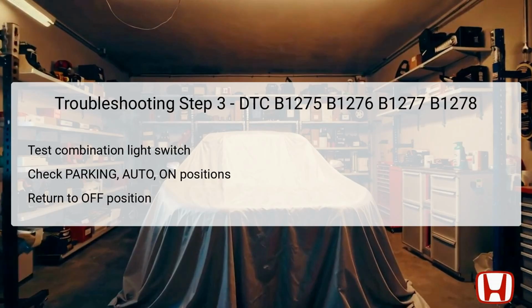Next, the combination light switch should be tested by turning it to the parking, auto, and on low beam positions before switching it back to the off position.